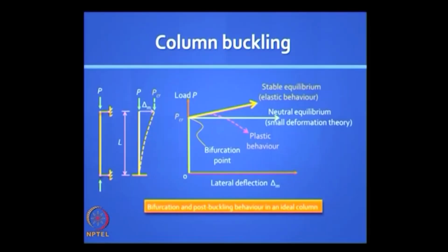So these things are well known. That is called large deformation analysis, which you do not normally study at an early level, but in elastic stability you get a solution like that. Okay, now if the two ends are simply supported or pinned like this, the buckle shape will look nicely symmetric, and this is a standard case which actually Euler explored, and this is called the Euler buckling load for the standard case where the solution is pi squared EI by L squared.